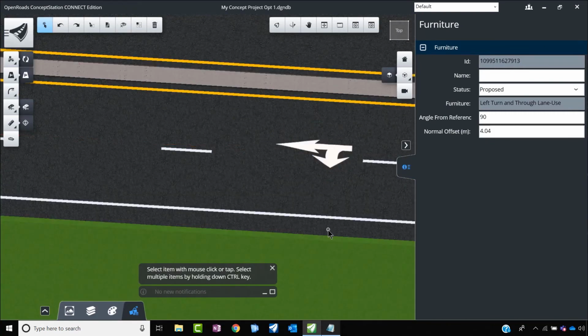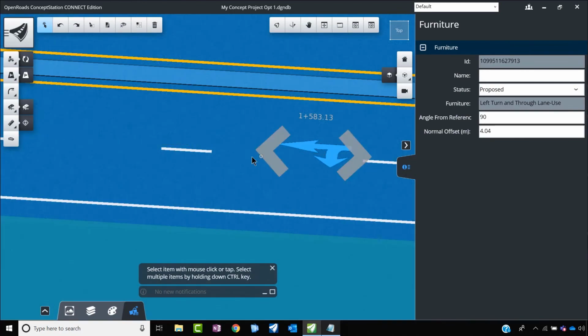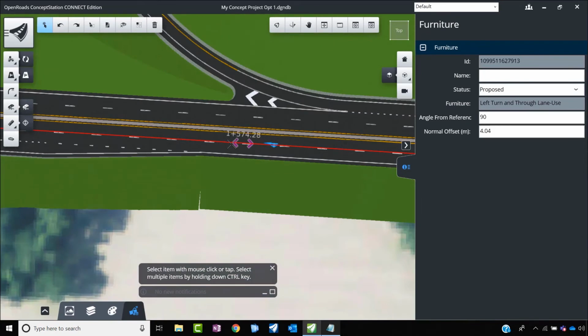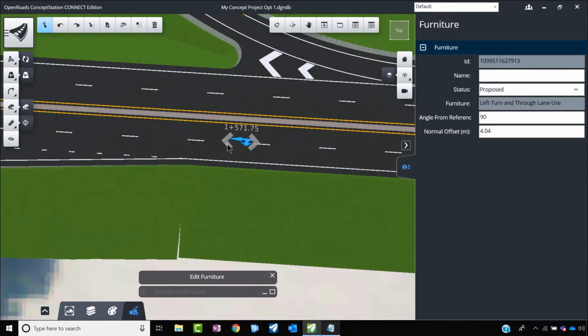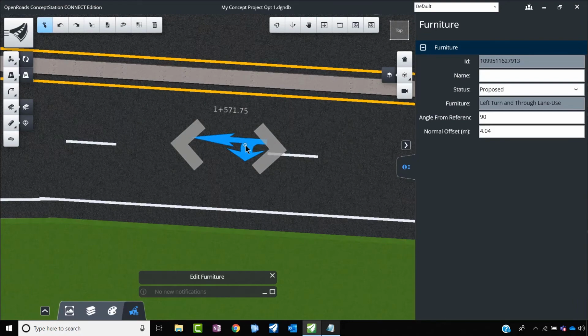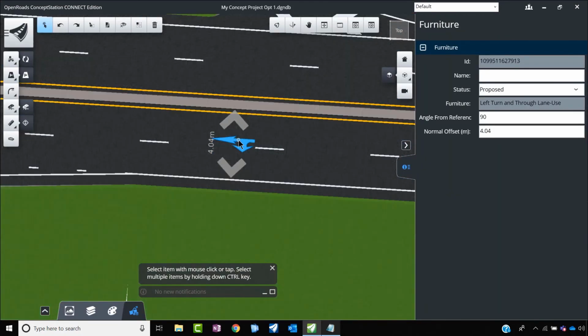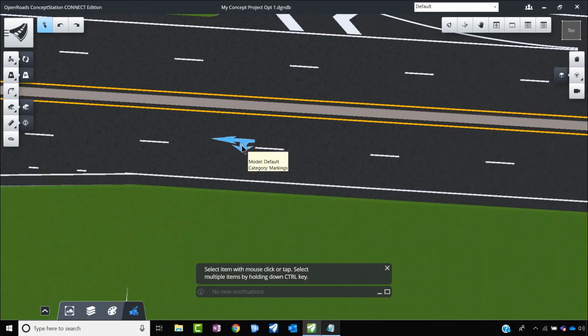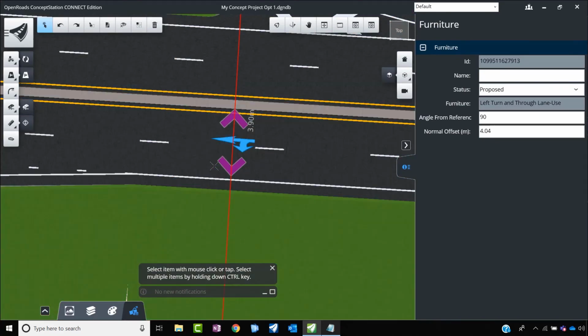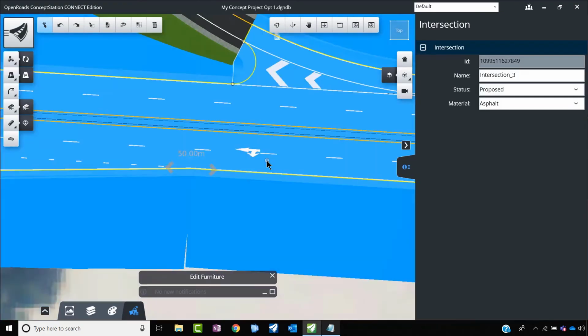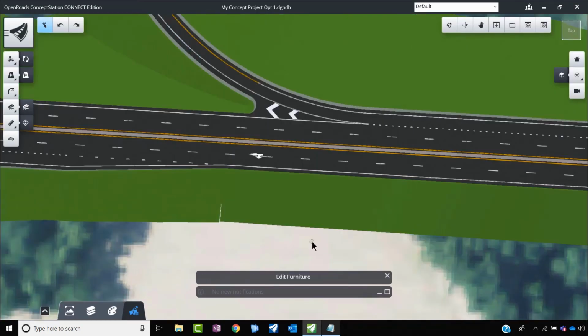If you select once, it shows in this direction where you could move the placement, and if you want to move it in a horizontal, select the next time. It will show you in what way you want to move in this, and the third time if you click, it will show you the rotation one. Click on that, come over here and select where exactly you want to place it, and you could place those road markings.